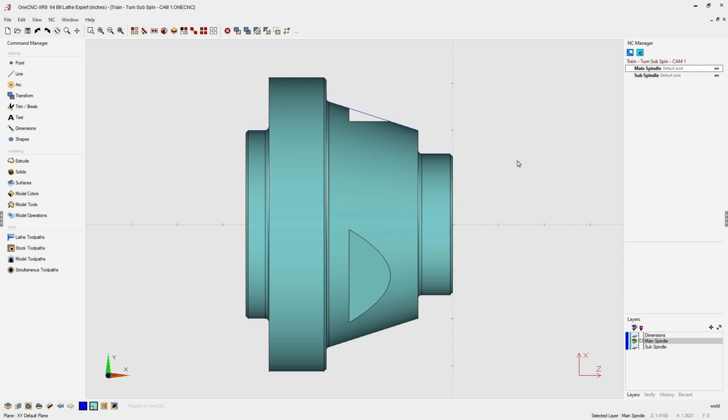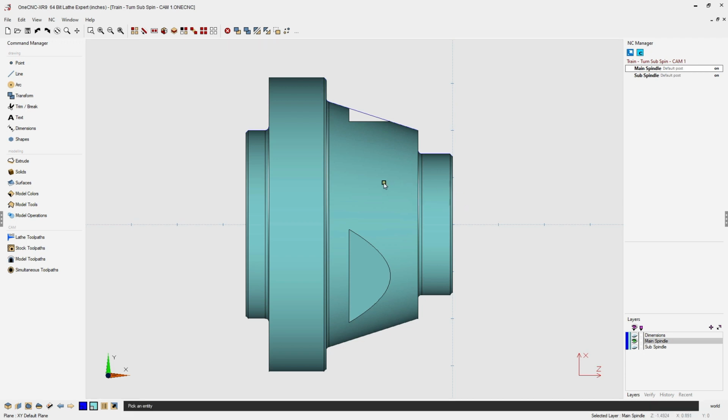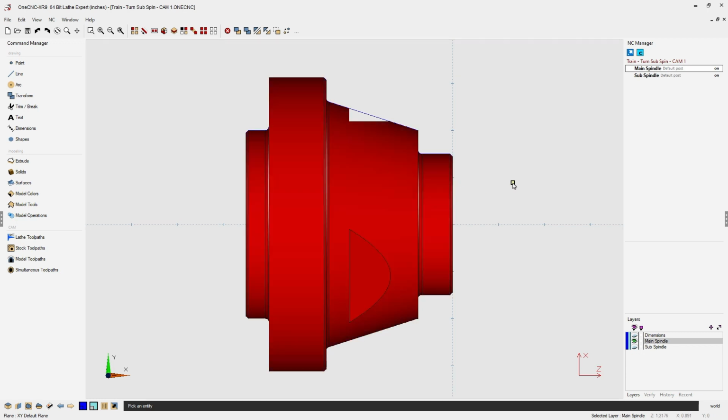You can certainly apply your toolpath right now to the wireframe geometry. However, if you want to, you might want to temporarily hide the solid model so you can just see the wireframe geometry. Let me demonstrate how to do that. What you want to do is hit the letter S on the keyboard to go into select mode. And once you've done that, you can take your cursor and left-click the solid model.